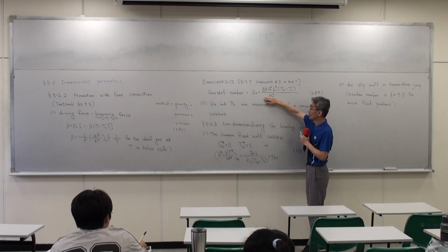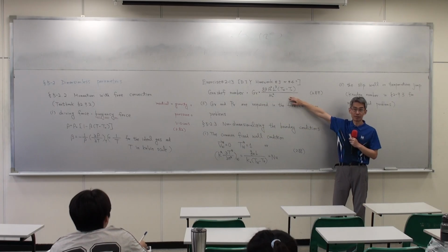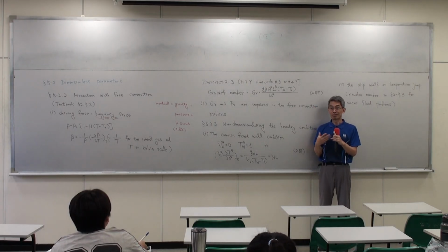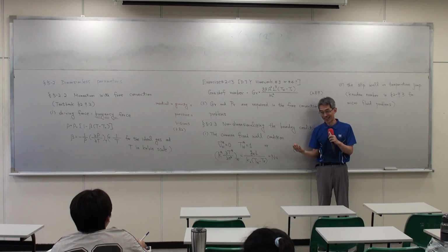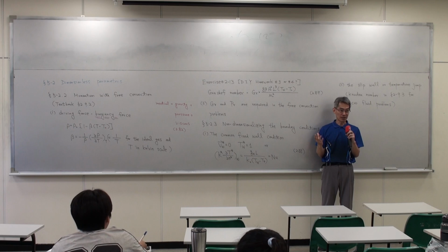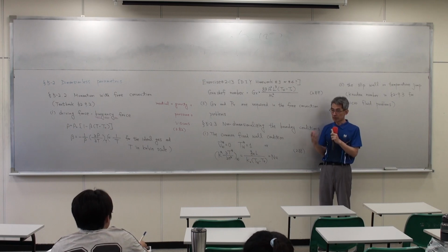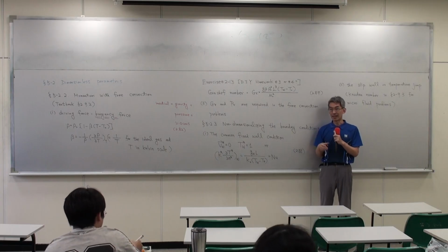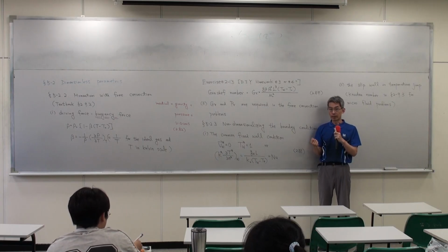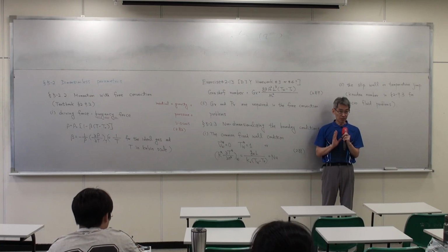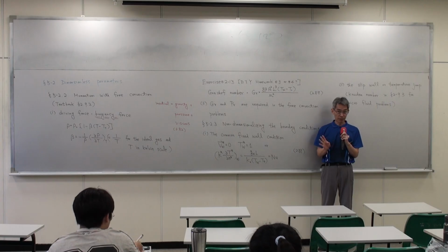Then this is what I would like to mention. Where does the Grashof number come from? It does not come from the mass continuity equation, right? The continuity equation doesn't produce any dimensionless number. Does it come from the momentum equation or from the energy equation? They have different meanings. From the momentum equation, it means a ratio of two different forces.